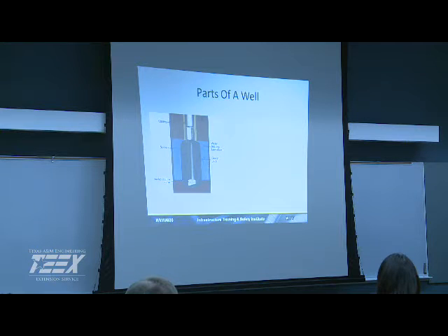Yep. Well, we were talking about that yesterday when we were going through the surface water treatment rule, and you start looking at your backwash filter rule. What can you discharge? What can you recycle? You're concentrating it, so you don't want to blend it right back up at the front of your plant. But if you're going to discharge it, now you've got to go in through a TPDES. You know, you've got to have a permit to discharge. So I mean, there's a lot of dynamics that go into all that. It can make your head hurt after a while if you get into it too far. But really interesting water stuff.